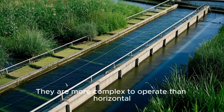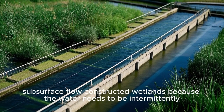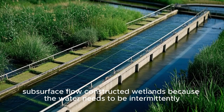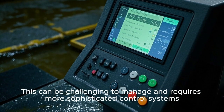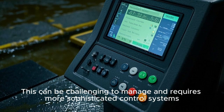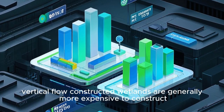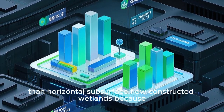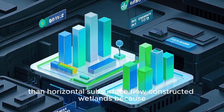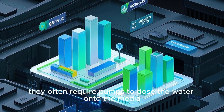They are more complex to operate than horizontal subsurface flow constructed wetlands because the water needs to be intermittently dosed onto the surface of the wetland. This can be challenging to manage and requires more sophisticated control systems. Additionally, vertical flow constructed wetlands are generally more expensive to construct than horizontal subsurface flow constructed wetlands because they often require pumps to dose the water onto the media.